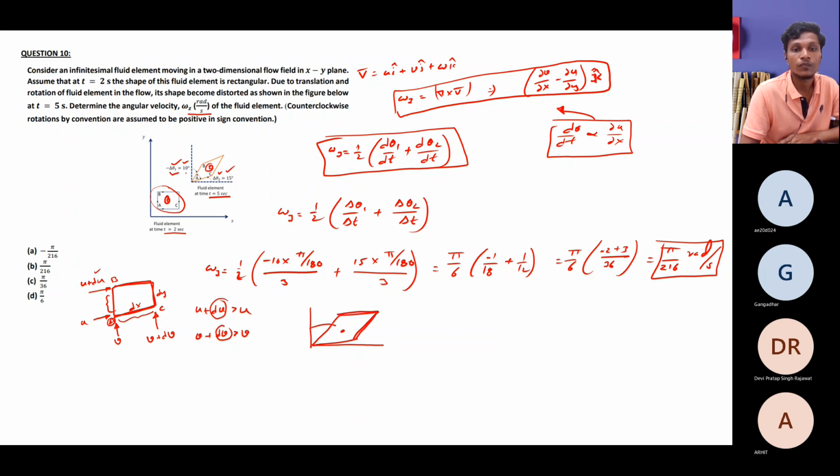Now you can see, from the y-axis, I have say approximately 45 degrees of rotation of this edge, but from the x-axis to this edge, there is say only 10 degrees of rotation. If there is a large difference in rotation, then what happens to the remaining 35 degrees of rotation? That means this particle has a tendency to rotate about its own center.